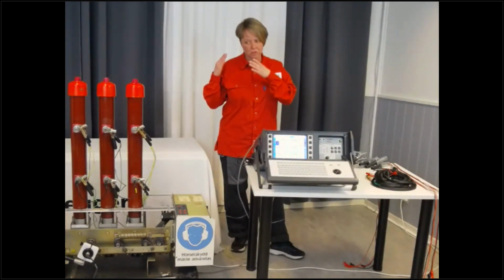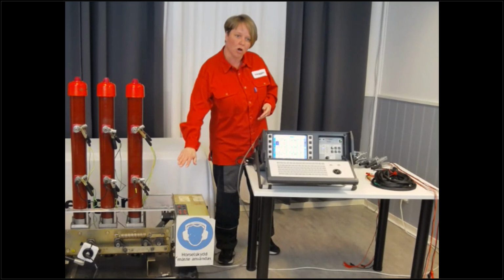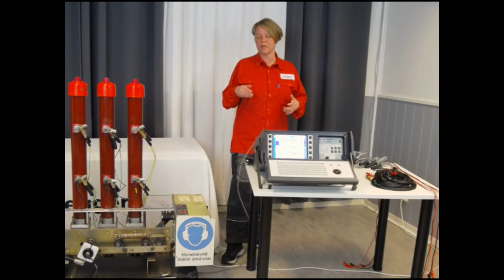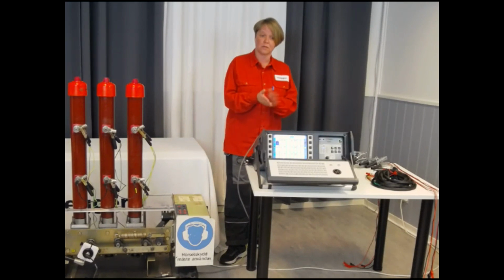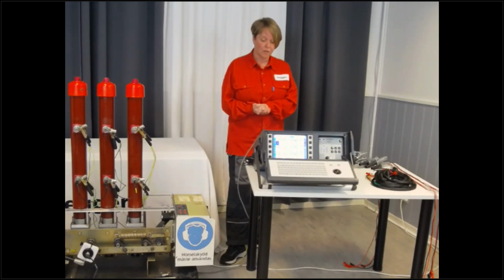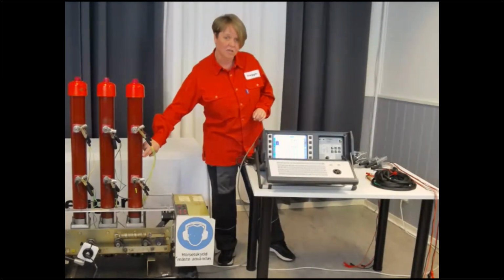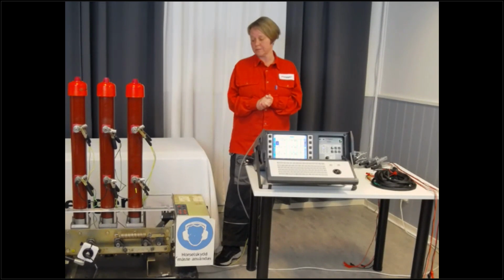We just tested the circuit breaker in a traditional way by supplying voltage over the phase and checking when we have a circuit. In some cases, we recommend doing this in another way, but then you need this bigger instrument to use something called dual ground timing. Another name for it is DCM. We call the module DCM. Normally you look at the circuit breaker as a resistance, but during this measurement, the instrument looks at it as if it were a capacitance instead. And we do a resonance frequency.